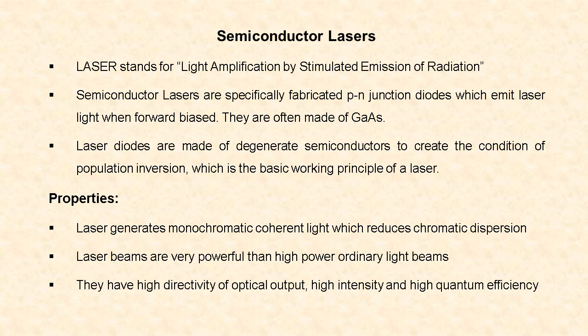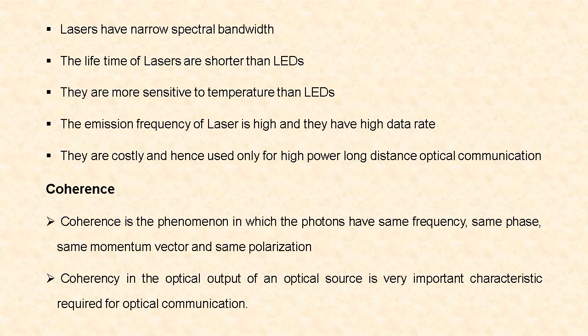Next, the laser beams are very powerful than high power ordinary light beams. They have high directivity of optical output, high intensity and high quantum efficiency, that is high output power. Lasers have narrow spectral bandwidth than LEDs. Their lifetime is shorter than LEDs and also they are more sensitive to temperature than LEDs, that is light emitting diodes. They have high emission frequency and high data rate.